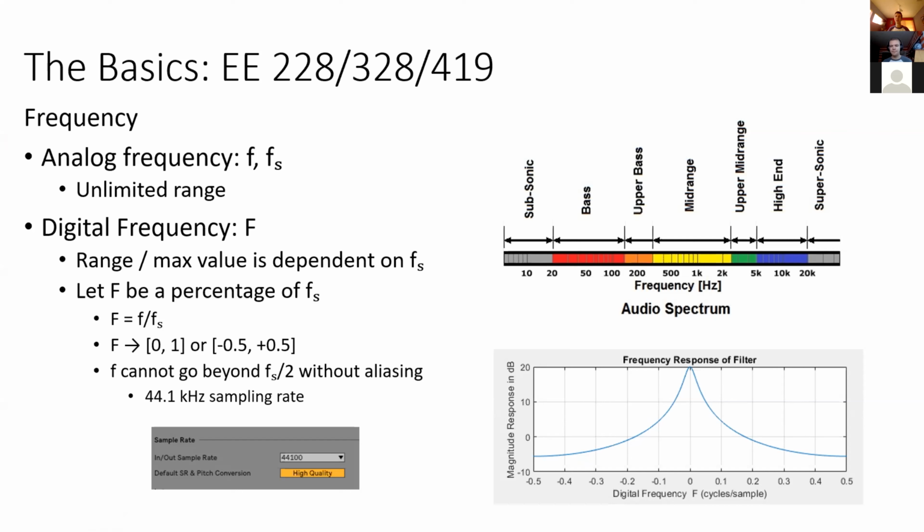rate without getting aliasing. It's basically a distortion to your signal. It means that you're not going to record the signal that you actually think you should be recording. So that's why modern systems, like in Ableton, which I opened up and it's recording at 44,100 samples per second. We can hear up to 20K. So if you record a little bit past that in terms of your sampling rate, then the max frequency you can record is like 22K, right?